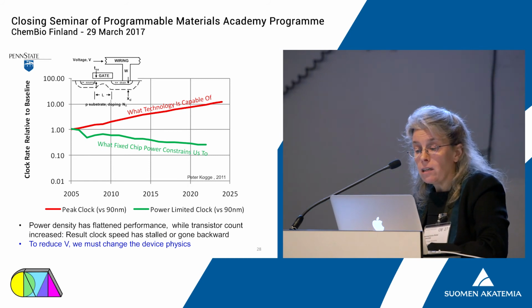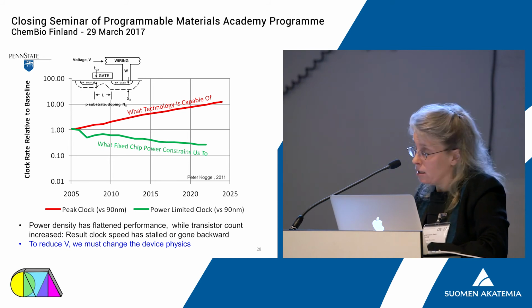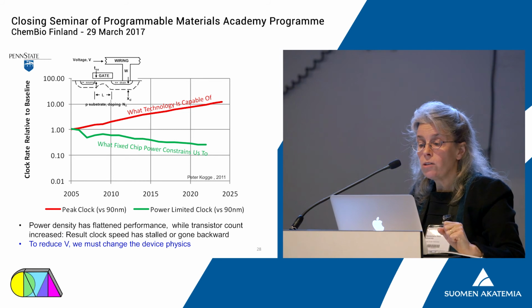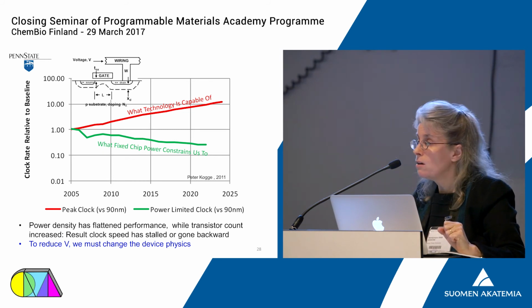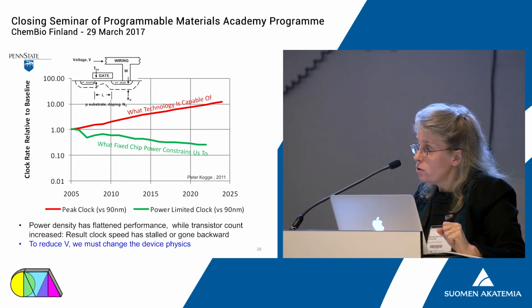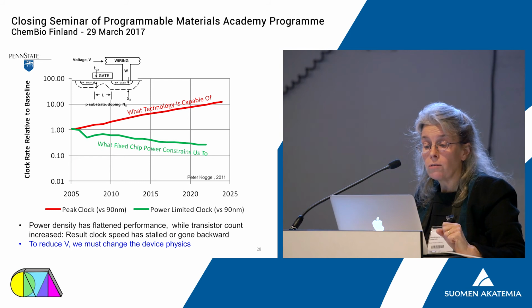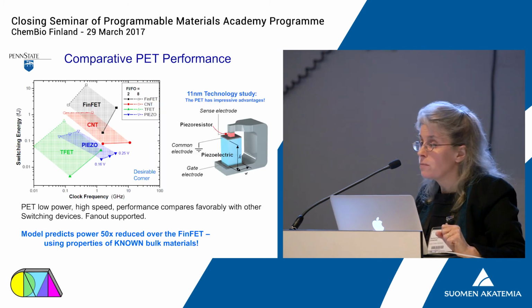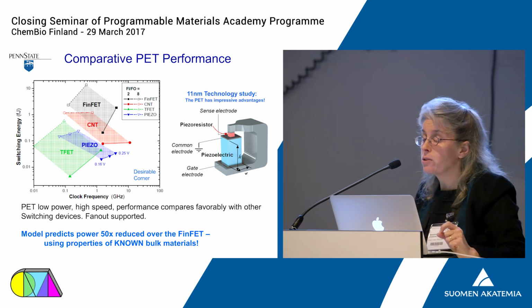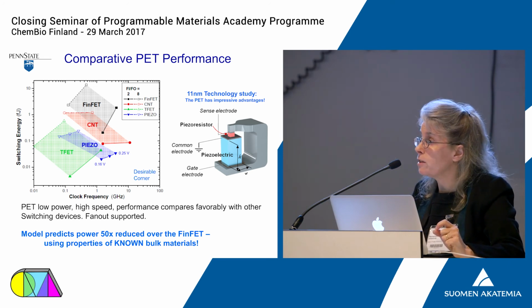And IBM came to me a number of years ago and said, we have a strange idea. We would like to take a piezoelectric material. Remember that piezoelectric materials elongate when you apply an electric field. And we want to use that elongation to compress a piezoresistor against a very stiff surround. If you can do that using properties of known bulk materials, a piezoelectronic device actually allows you to have low energies and higher clock speeds. So the estimate is that we should be able to take clock speeds up an order of magnitude while simultaneously dropping powers by factors of 50 to 100.